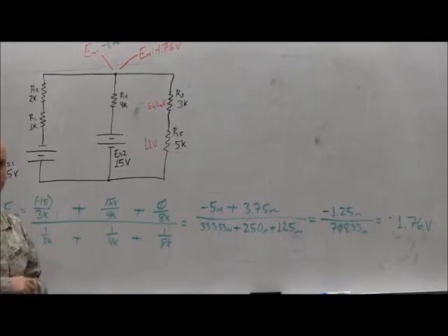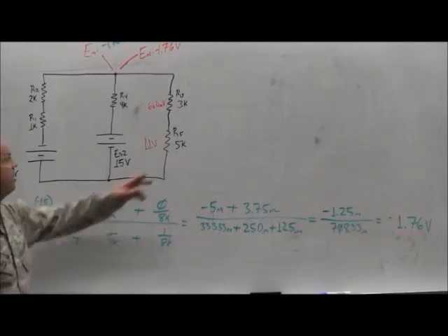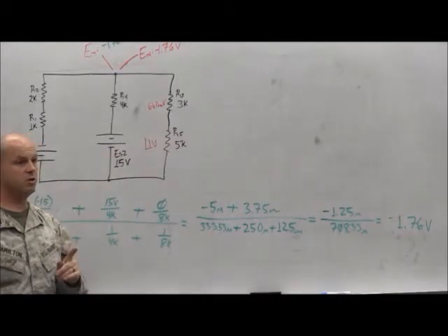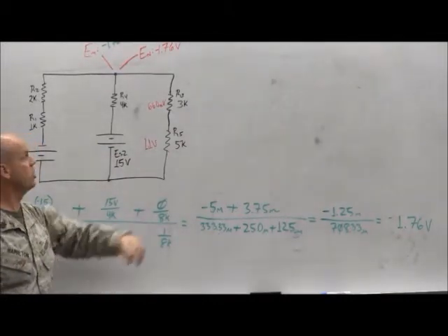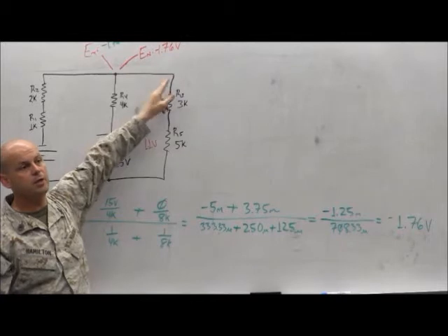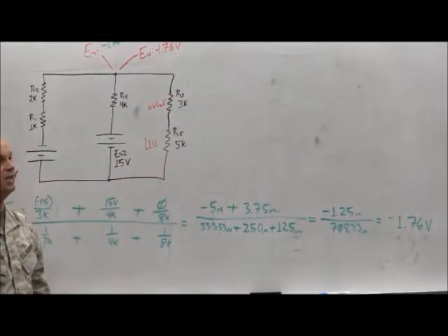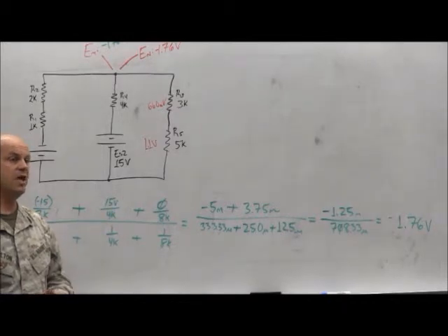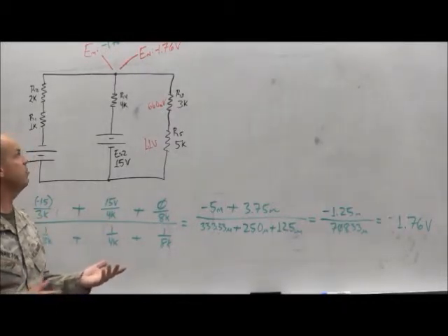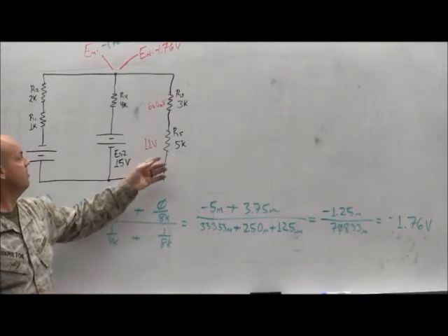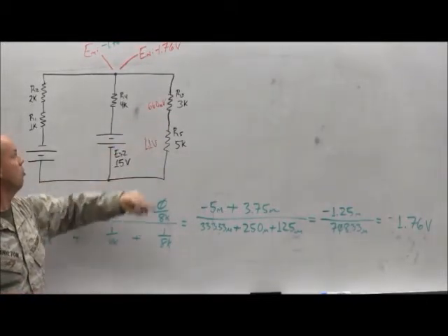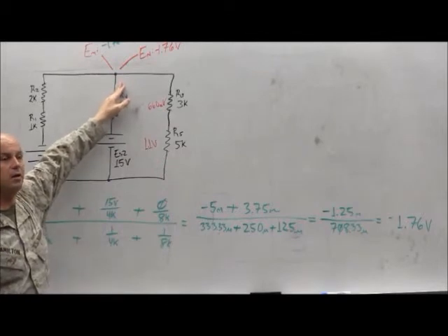Correct. But what did we first find out about Thevenin's? What did Thevenin's lead us to? The current. We found the current across this branch, right? Once we were able to find the current across that branch, the current up here, that allowed us to find the voltage drops. And then we said, if these are the voltage drops here, that wouldn't be any different than finding the nodal voltage right here, right?